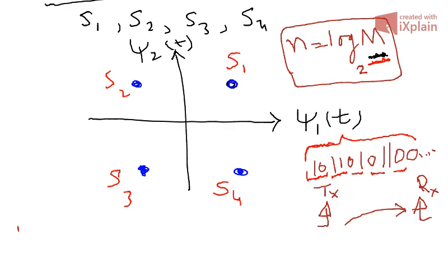When we group the data into two bits, we call it a di-bit. Now, what's the procedure? We will see it with the help of MATLAB as well. You have two bits in a di-bit, the first bit and the second bit. The first bit will be transmitted by the cos carrier, cos of 2 pi fct, and the second bit will be transmitted by the sine carrier.